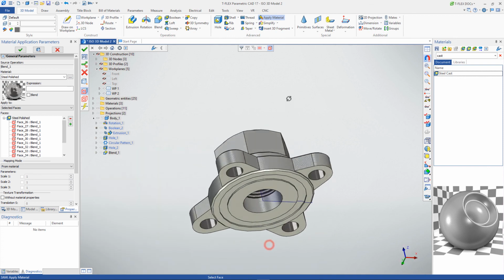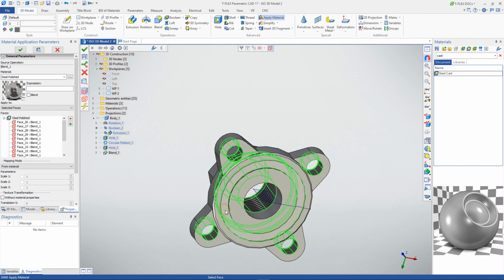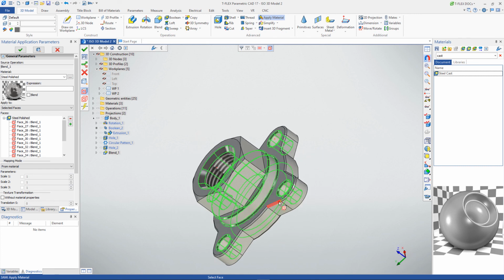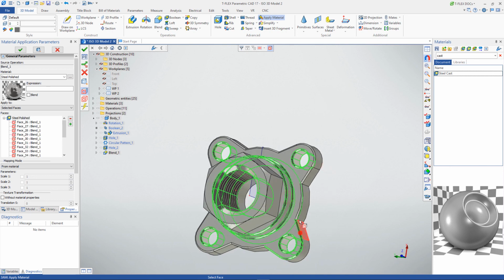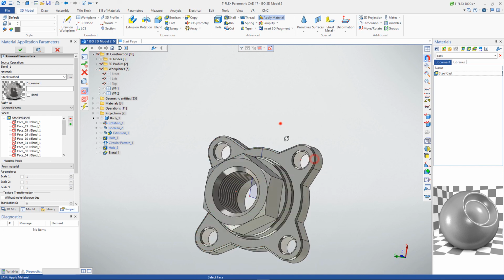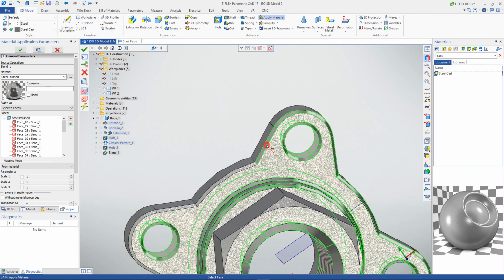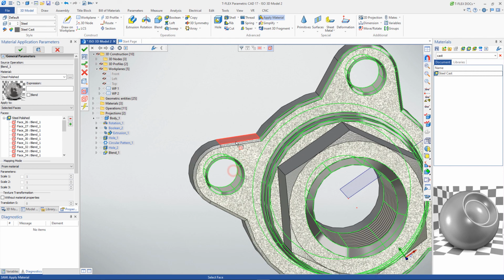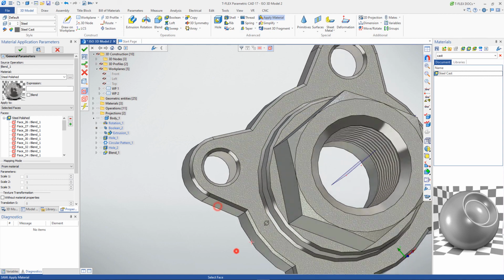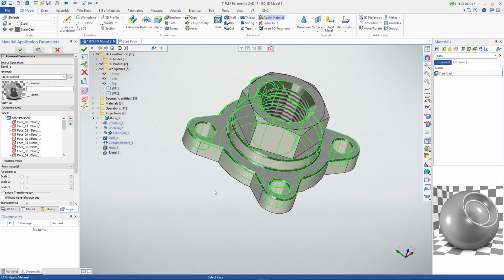In addition, we will select the end surface, as well as all the faces obtained by blending. If you mistakenly selected the wrong face, you can undo the changes by right-clicking, or by selecting the desired face in the Properties window and pressing the minus sign to remove it from the general list of faces. All faces are selected. Complete the input with a double click.